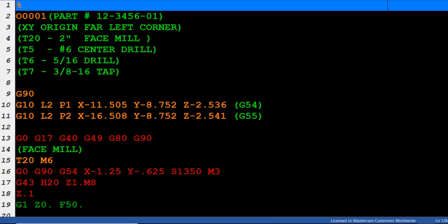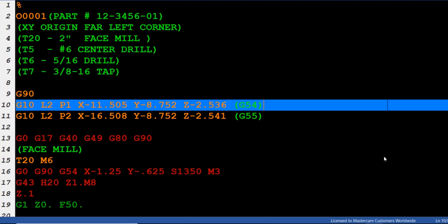In this video we're going to talk about the G10 command. The G10 command is a line at the top of the program that will automatically load a work offset into your work offset data page in your control. This is mainly done in production environments where fixturing allows you to use the same work offsets even once it's been taken out and then put back into the machine, because of dowel pins or a type of fixturing that repeats the same location from one job to the next.